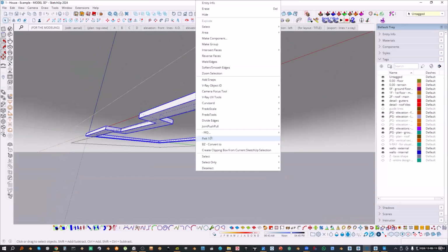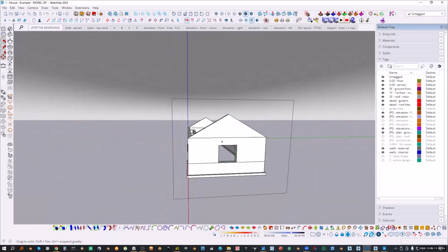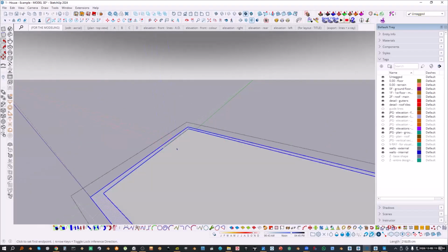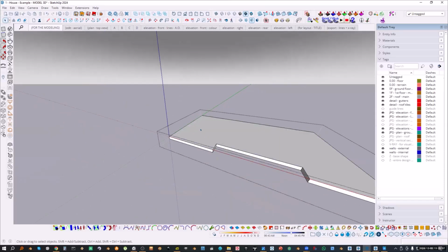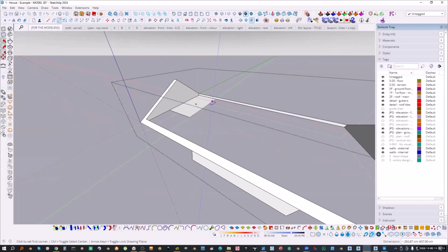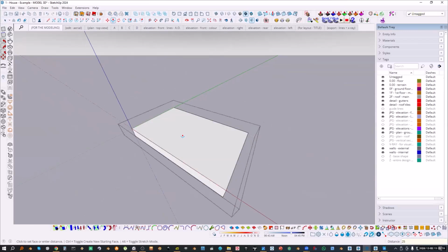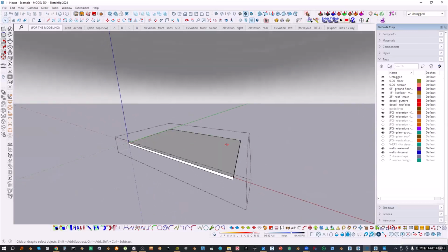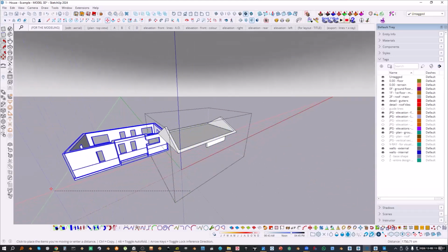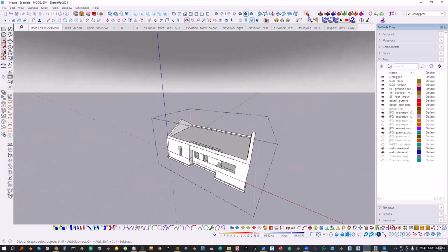And now, again, Fix-It 101. Now we have that, and basically that building starts to take shape. We're getting there. Let me just make the floor quickly, maybe 30 centimeters. And the top floor, I mean the first floor, also the slab, maybe 28. Okay, so now we have those two pieces, and we could put that on the tag as well, it used to be called layer, to have easier access to the inside of the building.